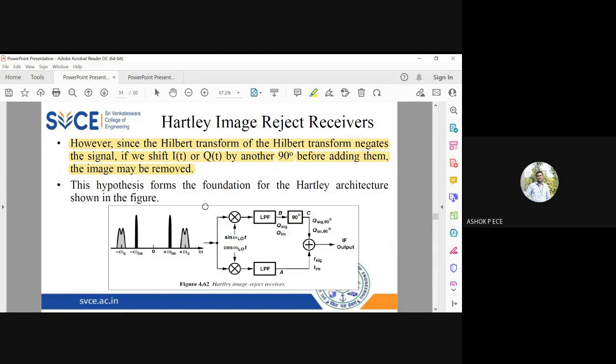See here. This is a conventional architecture where we multiply with phase shifted values of the local oscillator. After that, you ensure that you select only your appropriate channel, and you do one more phase shift. The in-phase signal will come directly to the output, but the quadrature phase will be shifted by 90 degrees, and that output you will get in the upper arm.